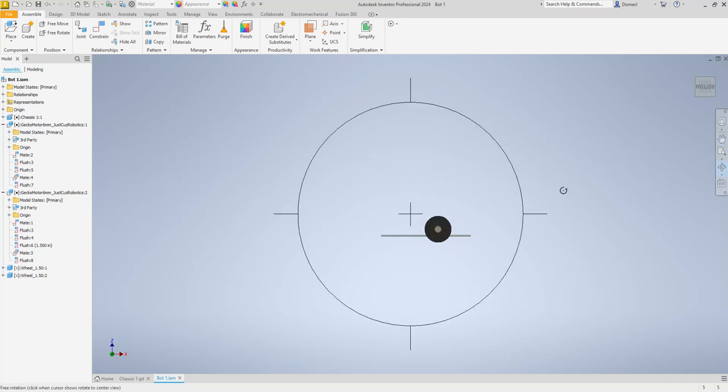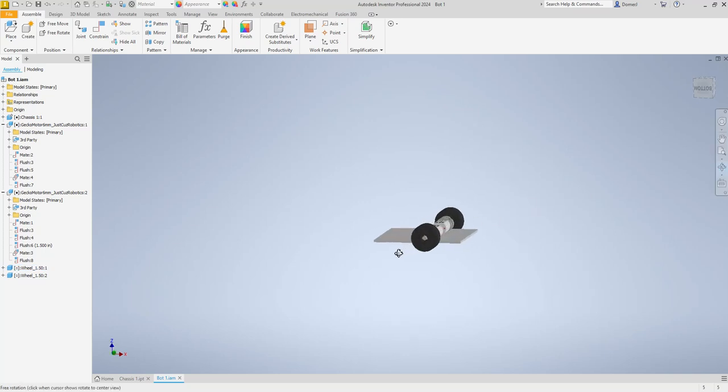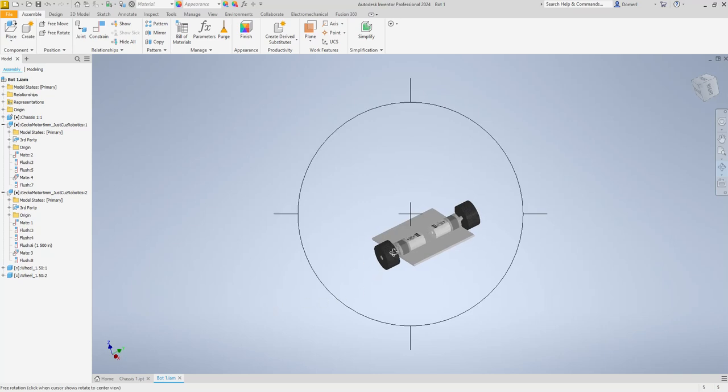So how do I, two ways to get less ground clearance. Throw an idea out there. How can I get less ground clearance? Motor higher or smaller wheel. I'm going to make the motor higher. I think that's a better choice. Gives me a little bit more meat to make a mount for the motor anyways. Right now there's really nothing to mount that motor with that design.